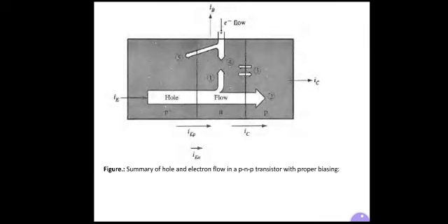The second one: some electrons will be injected from N to P in the forward biased emitter junction, even if the emitter is heavily doped compared with the base. So these electrons must also be supplied by IB, that is, the base current. And the third one is that some electrons are swept into the base at the reverse biased collector junction due to thermal generation in the collector. So this small current reduces the base current IB by supplying electrons to the base.